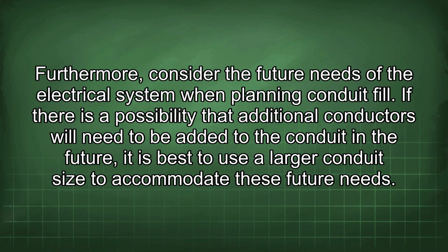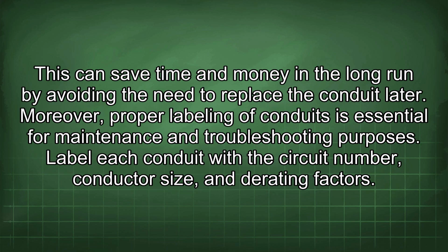Furthermore, consider the future needs of the electrical system when planning conduit fill. If there is a possibility that additional conductors will need to be added to the conduit in the future, it is best to use a larger conduit size to accommodate these future needs. This can save time and money in the long run by avoiding the need to replace the conduit later.